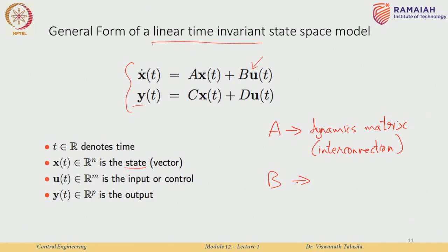Now, okay, before I go ahead, please note the dimensions of the matrices are very important. So, let us say we are looking at an nth order state space system, and remember that you get an nth order state space system typically from an nth order differential equation, all right. So, if you have an nth order state space system, the matrix A will be of dimension n cross n, it cannot be more, it is a square matrix of dimension n cross n.